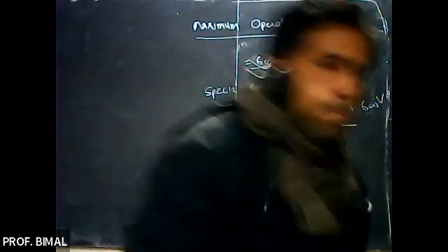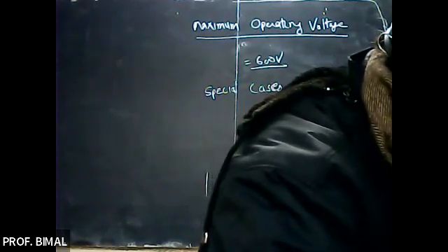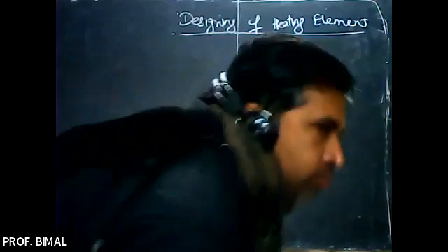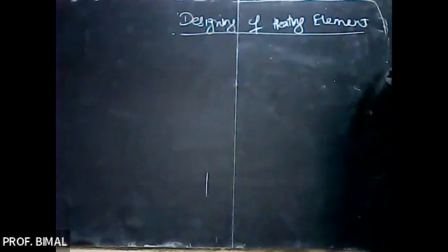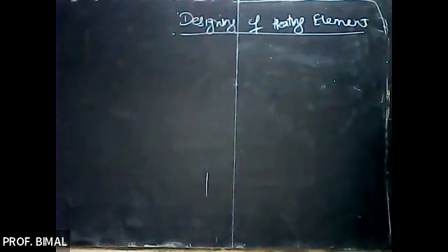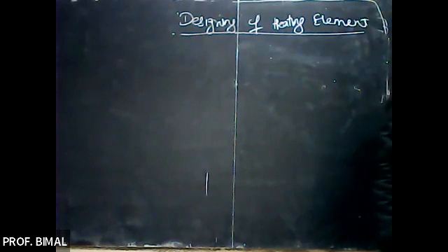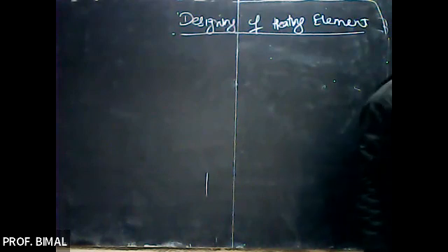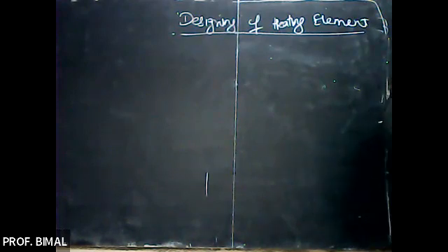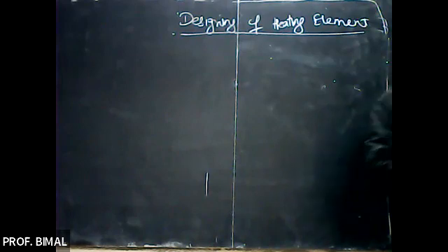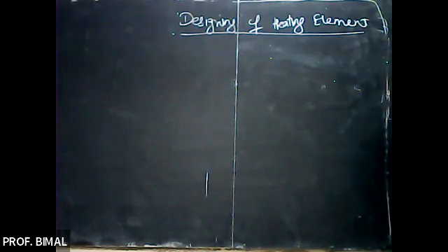Then, yes, next is the designing of the heating element. Now, if we are aware of the electrical input and its voltage, the size and length of the wire required as the heating element to produce the given temperature can be calculated, right?